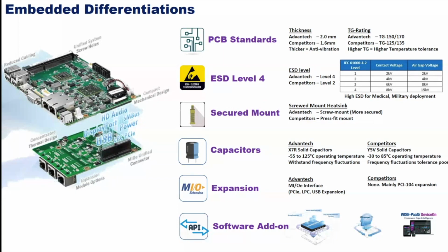In actual fact, board bending can be quite a big issue because it's hard to trace. It's usually signal integrity, and you end up not knowing what is wrong with the board. It's very hard to trace the actual fault. 1 divided by 180 is the maximum a board can tolerate before it starts to bend. So ours has a much stricter PCB design.